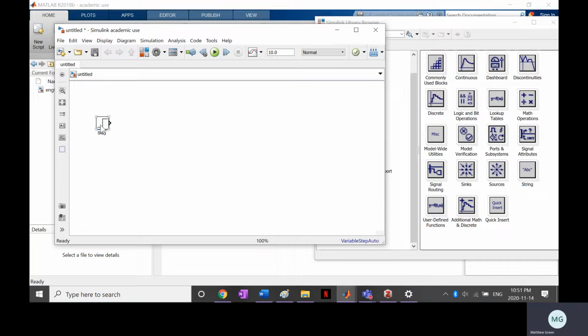And then next, that's our input, our source. And then we want to have an output as well. And our output is we're just going to show everything. And for that, what we want to use is a scope. And the scope, you can change the amount of input ports. So we're going to have two input ports. The first input port is going to be for the step directly. And the second, because that's going to show basically how the system responds directly to the step.